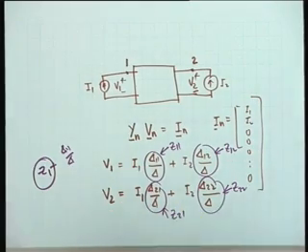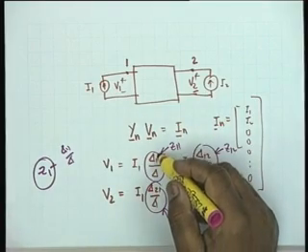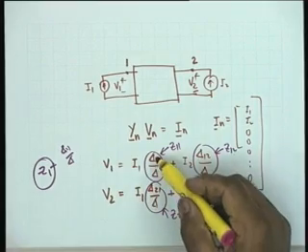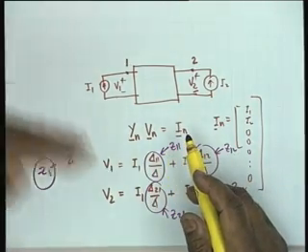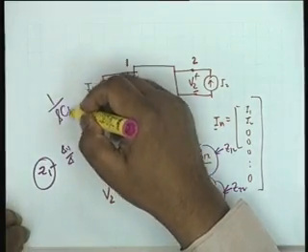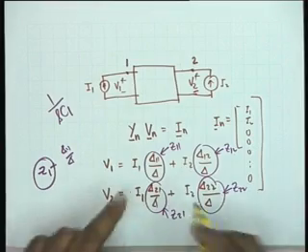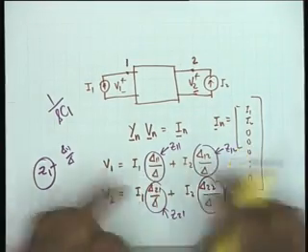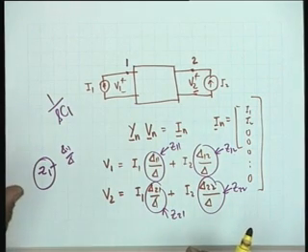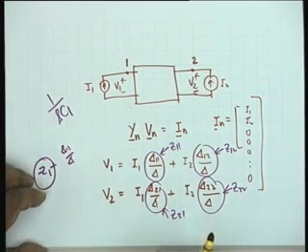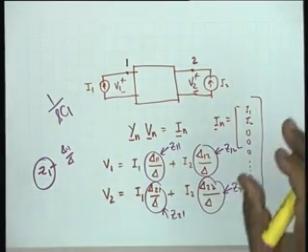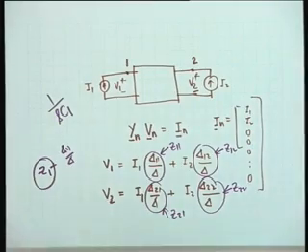You see, what you are going to do ultimately is that del 11 and del both in general will be rational functions. And what you will do is you will make this into a polynomial divided by polynomial by clearing inverse expressions like 1 by SC1 and so on. So the denominators of all these rational functions will be the same. Correct? And therefore the zeros of the denominator shall occur at the same point. Poles must in general be shared. On the other hand, there are exceptions with regard to Z11 and Z22 because we can add anything in series. It does not affect Z12.